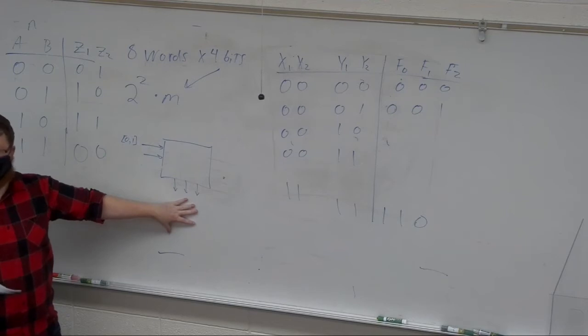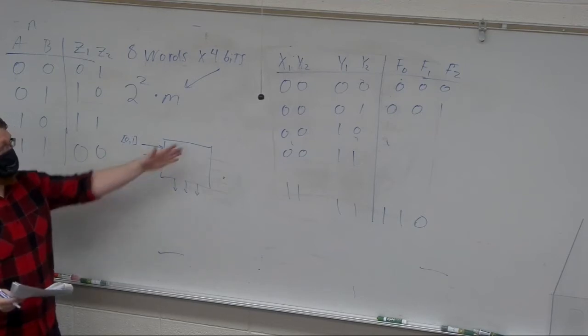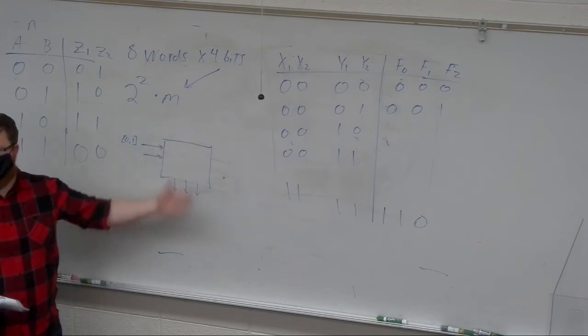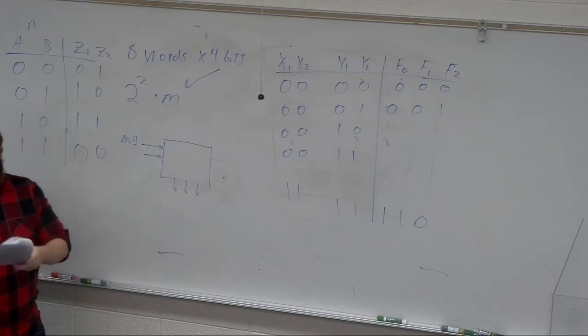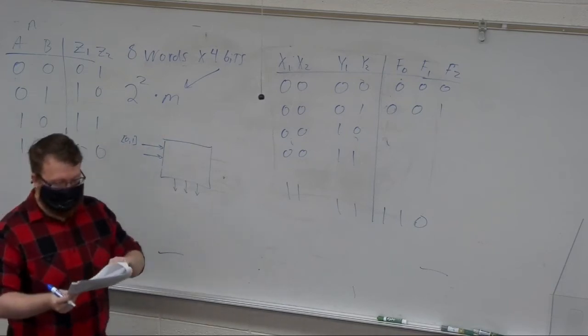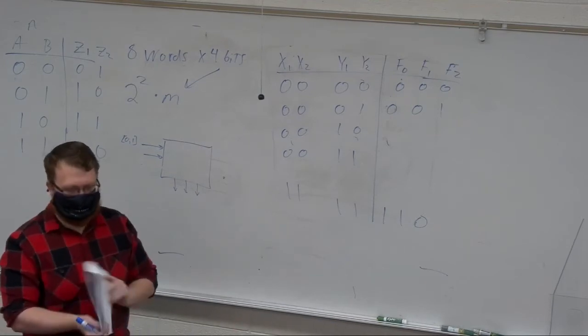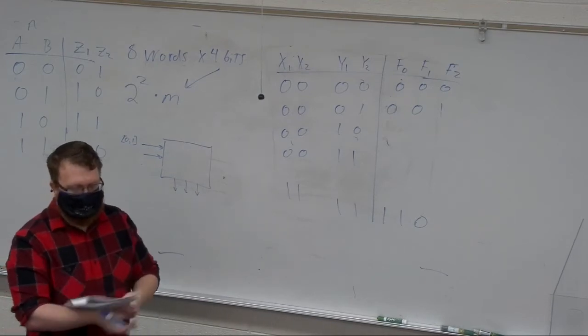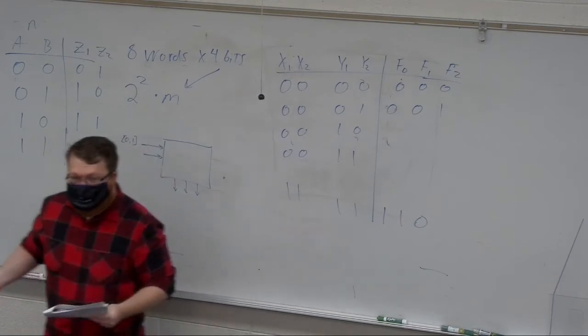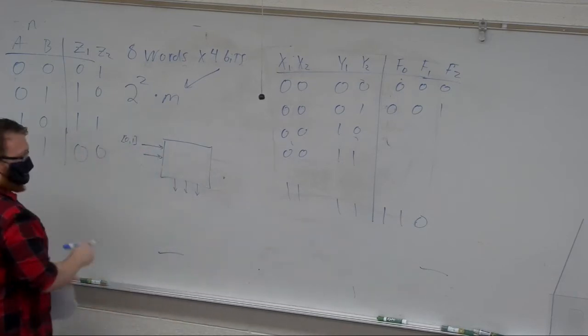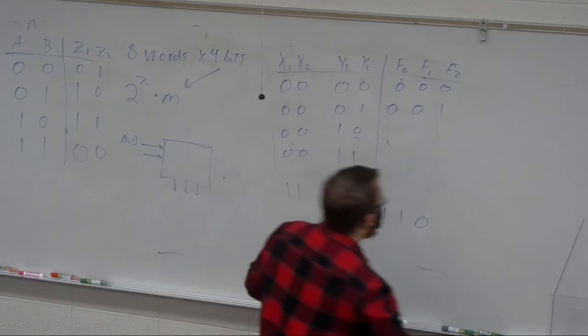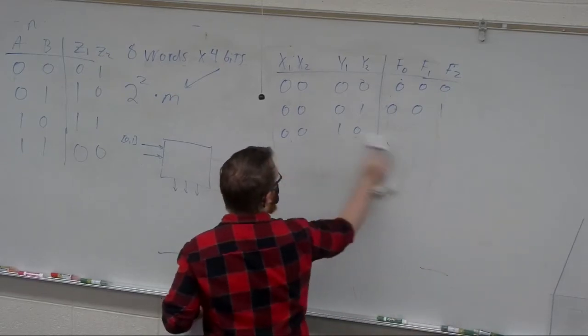You put these values in, this does some math. And, well, no, I take that back. It doesn't do any math. It just looks up what you told it it's supposed to be and outputs it. Done. That's all a ROM is doing. And it's not especially clever on the internal workings, but it is useful. They get more useful because you can actually turn these guys pretty easily into a state machine.